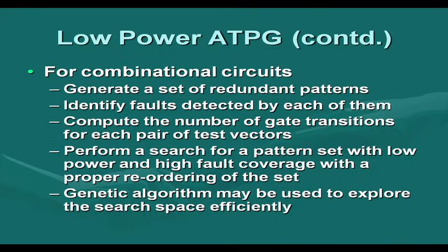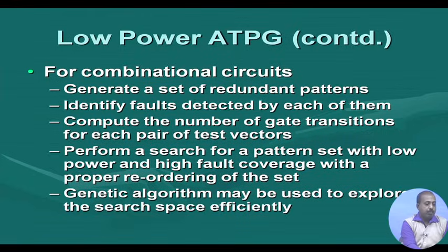If we do not do a fault coverage analysis, then of course it will select pattern pairs which consume low power, but the fault coverage value will be low. As a result, we need to apply a large number of patterns. Maybe finally we will end up applying more patterns, and as a result the power consumption increases. So we perform a search for a pattern set with low power and high fault coverage with a proper reordering of the set. The procedure that I have described definitely gives us the ordering also, the order in which the pattern set has to be applied so that the power consumption is less.